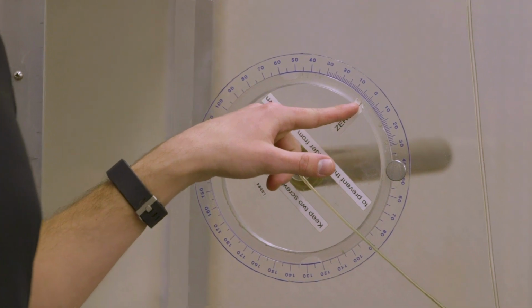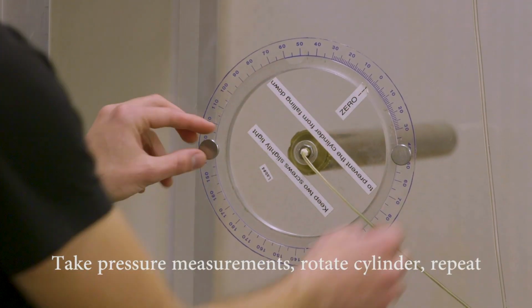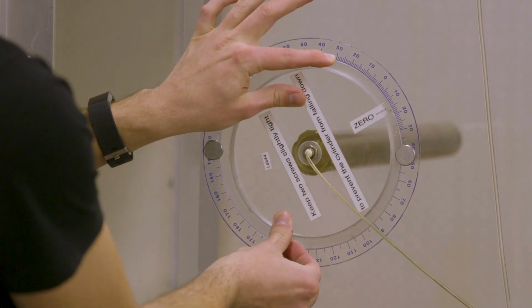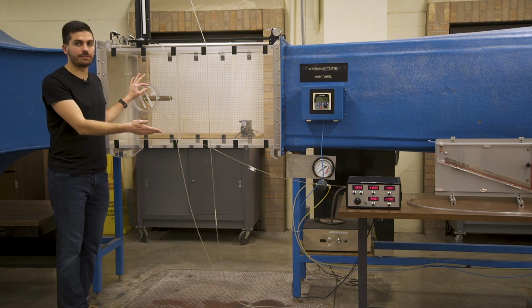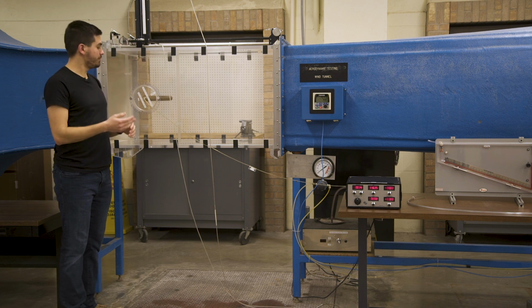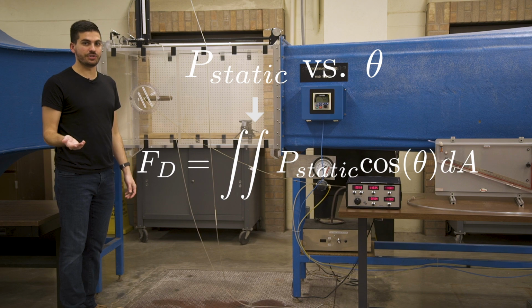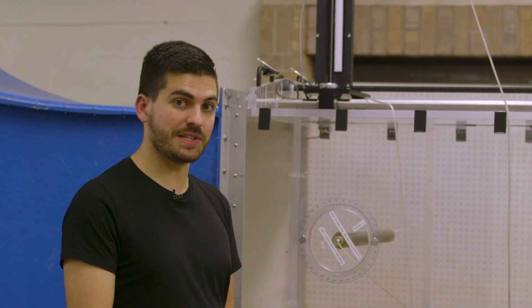So as I mentioned earlier, we'll be taking pressure measurements in increments of 10 degrees by rotating the cylinder as such, and marking down the digital readout from the pressure transducer along the way. That way we'll have pressure as a function of angle along the surface, and that will allow us to integrate the pressure distribution and find the drag force. And we'll do this at both 15 meters per second mainstream flow and 30 meters per second.